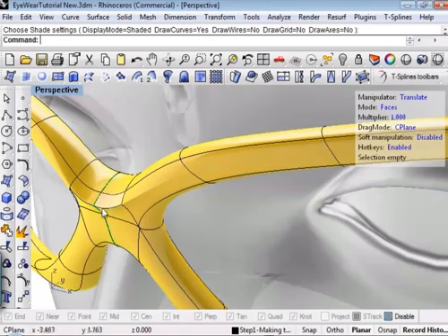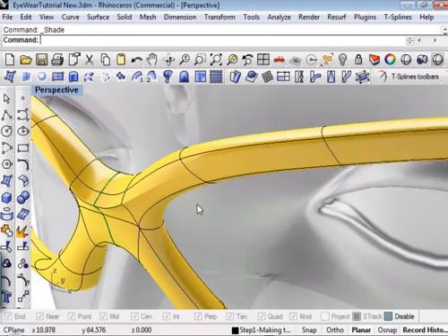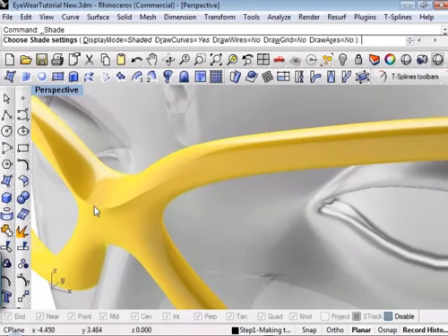So if you want to crease a surface and have the crease be localized here, it's not going to happen. What's going to happen is the crease is going to have a value of 1 here. I'm making this up. Tom is probably cringing at me doing computer math here as an art student, but let's say this crease has a value of 1 throughout this entire surface. It has a value of 1 here and a value of 0.5 here, and then a value of 0.5 here and 0 here. So if I shade this, you'll notice that the crease starts and then takes 2 entire faces to fade out.